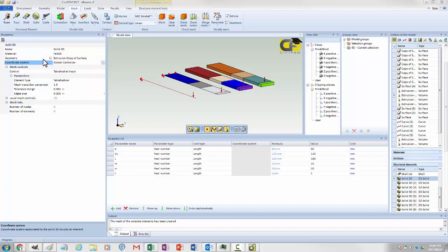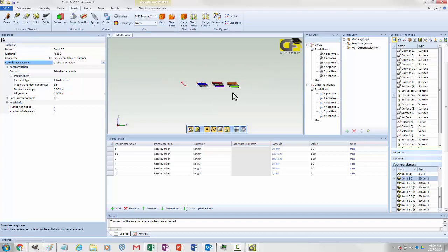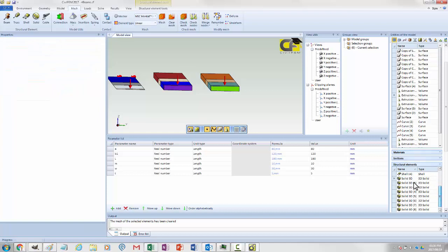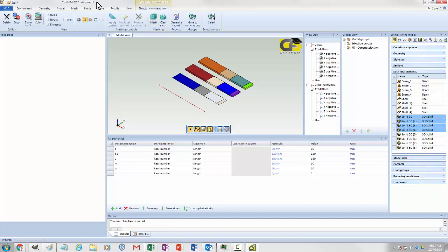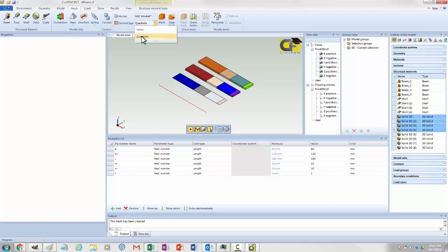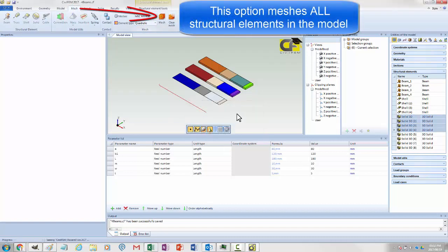And indeed what I see over here is that we've set up the element type to be linear, which is quite a bad formulation for these tetrahedral elements. So for the tetrahedral elements, which are these guys, let's just change that. For these elements, we should mesh them with quadratic elements instead, so that it creates mid-side nodes for the tetrahedral elements.